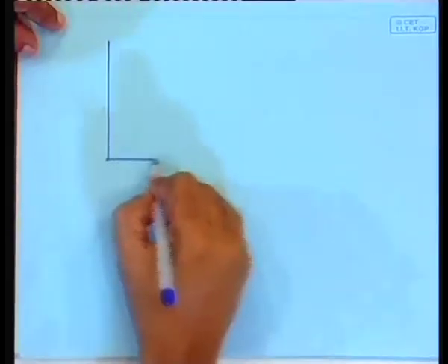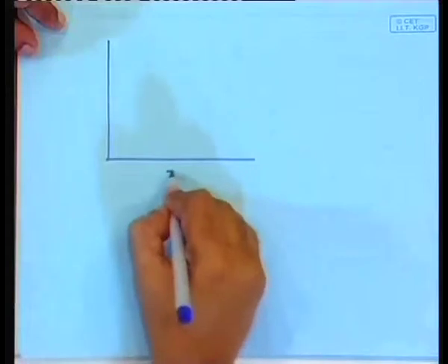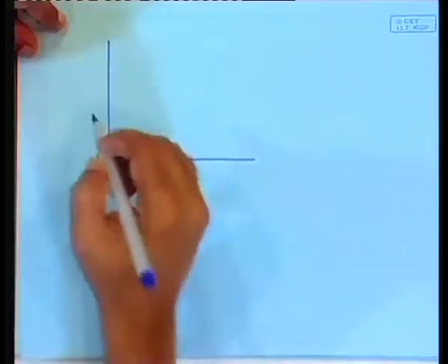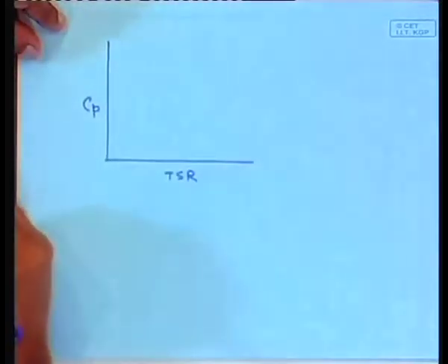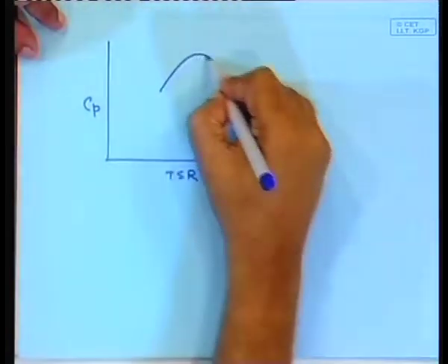What it leaves us is the issue of pitch control. Now, about that we have understood a few things. Firstly, we have understood in the last few lectures that the tip speed ratio versus Cp, power coefficient characteristics, is like this.